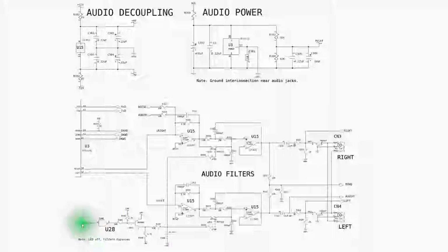There is this audio filter switching circuit here. And if the audio filter switching circuit is on, these 2 MOSFETs are turned on. Essentially creates a short across the resistors here and removes the filtering that goes on here to help filter the signal. So I find this kind of an interesting little circuit. So this filtering can be turned on or off with this digital pin here.